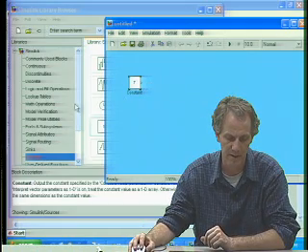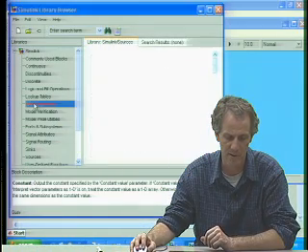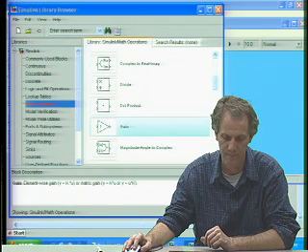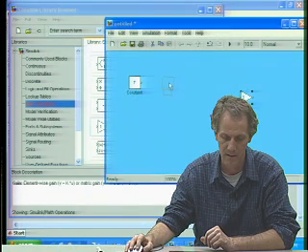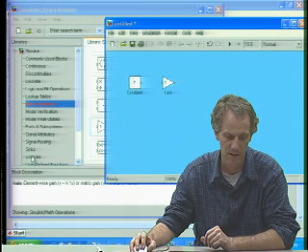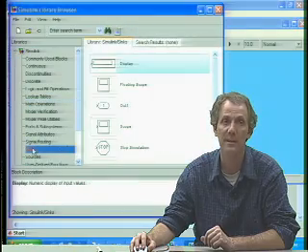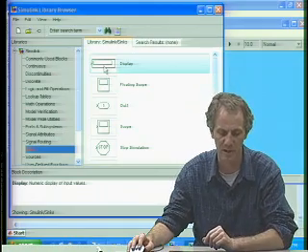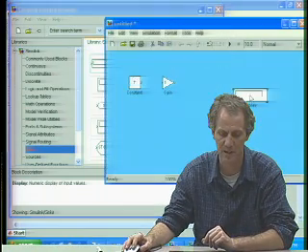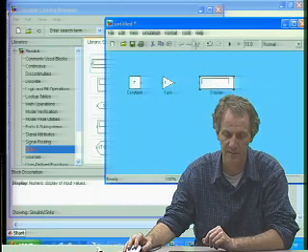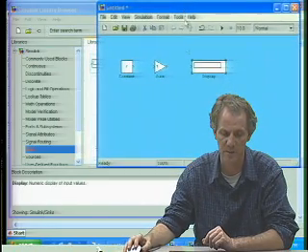And so I'm going to run it into a math operation called gain. And then I'm going to simply display that answer with a sink. Sinks are the blocks that only have an input to the block. Nothing comes out of the block. And the simplest possible sink is display. It's only good for displaying constants, but that's what we have here. So I'll grab the display block.